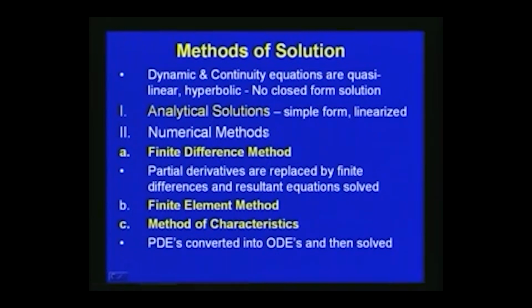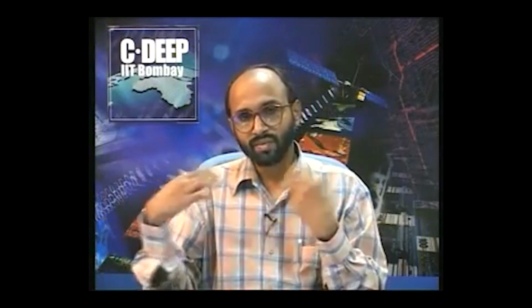Using either the finite difference method, the finite element method, or other methods like the boundary element method, finite volume method, or method of characteristics, a number of software packages are available for unsteady flow through pipes or closed conduits, which we can directly utilize.